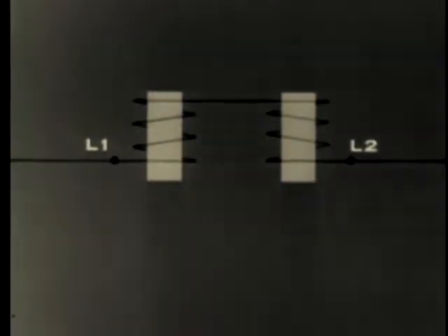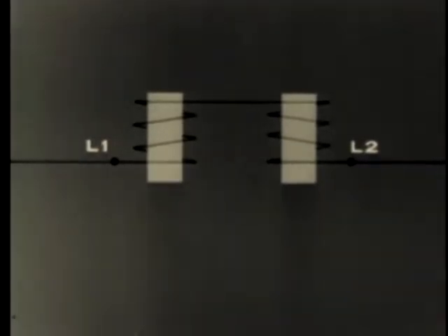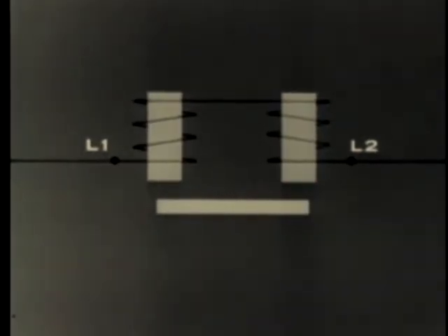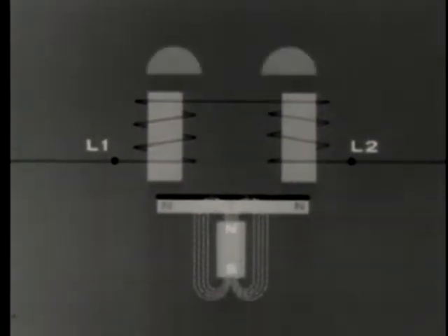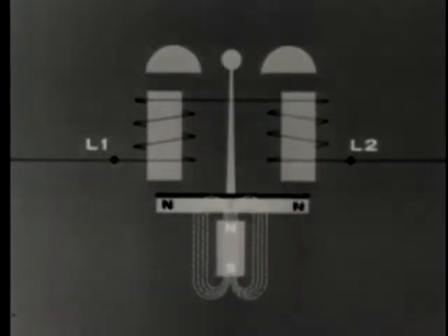When 2 soft iron cores are wound oppositely with wire, they become electromagnets whose polarity will change as the current in our line alternates. If we introduce a soft iron armature near the base of an electromagnet, and then introduce a permanent magnet to polarize the ends of the armature, an unstable condition will exist when current flows.